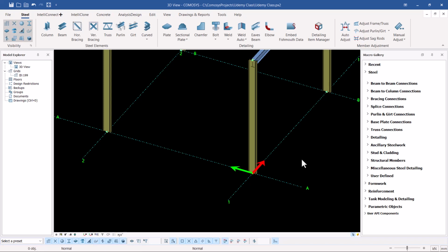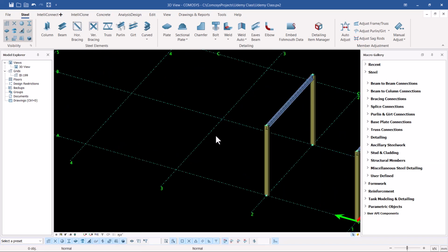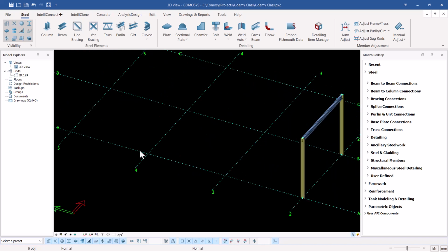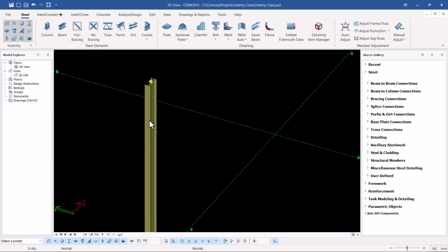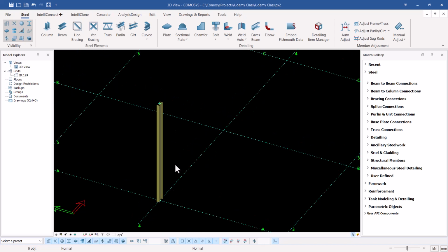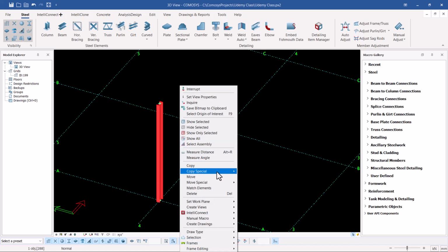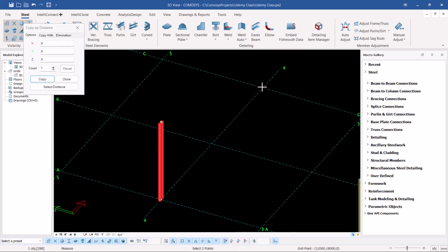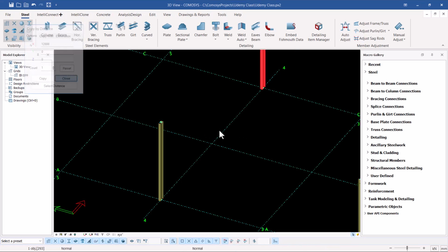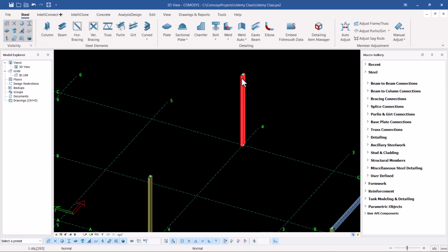Now, in our case here, I want to bring up a simple structure like we have a beam here. We have a beam here, and let me just turn that by pressing Control Q to turn that in an orientation that will favor our rafter placement. So I'll select on that member, then come to spatial copy here and pick on linear, and I want to place another beam on the other end. I'll define that by distance and click on that and click copy.